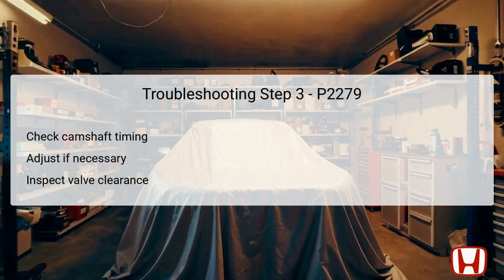Valve clearance refers to the gap between the rocker arm and the valve stem, which must also meet defined specifications to maintain optimal engine performance. Failure to set these parameters correctly can result in further misfires or inefficient engine operation. Completing these checks thoroughly may resolve the underlying issue indicated by the DTC.